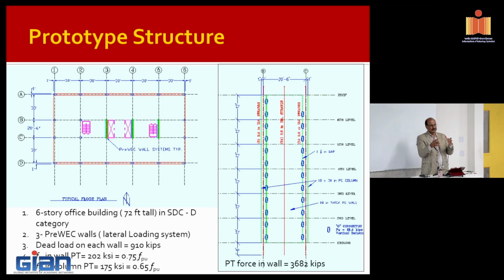Now, the energy dissipation associated with that comes with it because you already decided the moment resistance, the plastification of, if you have 20 bars, they are providing. I'm not controlling the damping. But since these structures were performing well, back in the days they calculated the equivalent viscous damping and said, okay, you should have 30%, then everything is going to be fine.